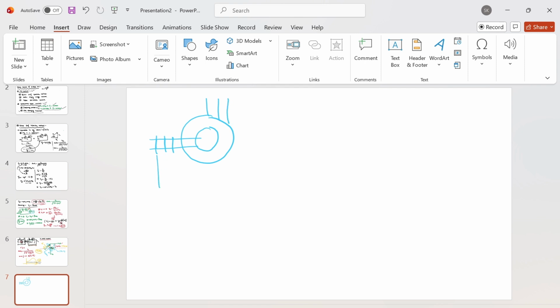And in the rotor circuit you are injecting voltage with the help of inverters and all. So let's say you have this AC supply and DC. You have to convert the AC to DC because this AC is at slip frequency, and then again you can convert this DC to AC of the required frequency, and you can inject this power to the grid, okay?